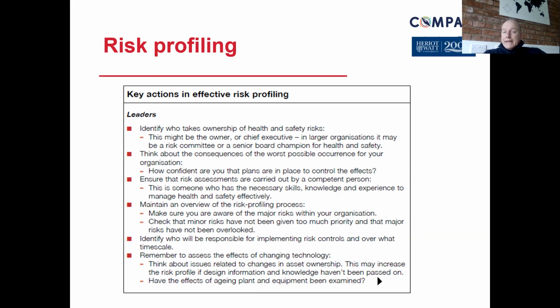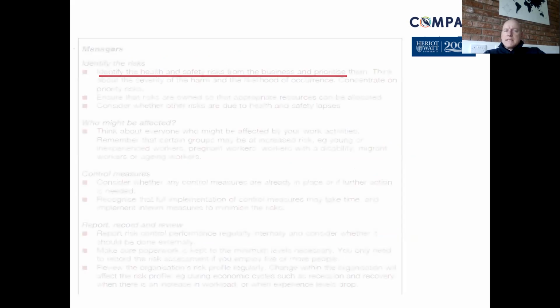So within manual handling, it will say use mechanical handling equipment as an alternative. Quite often, the investment in forklift trucks, for example, can increase risks to pedestrians and damage to property, but it certainly takes away that manual handling aspect. So whatever you do in the investment of changing technology, it's got to be, again, controlled, new risk assessments done, people trained up and made as safe as any other process within your system. So a consistent approach.